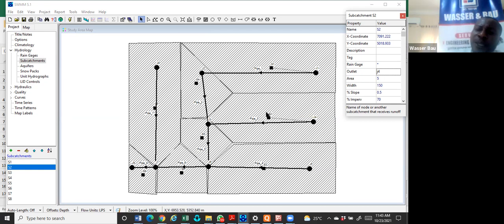So you know, gentlemen, the water that is coming from your house, when it comes out of your house, will enter the first manhole in front of your house. The water from your streets, when it leaves your streets, will enter the manhole on the road, on the major expressway. I want us to put on our imagination. So every catchment, water that is coming from Adeosun Street, Ozumbambadiwe, for instance, there's a particular manhole in front of Ozumbambadiwe that the flow will enter. So from that hole, it will then enter the pipe. So it is important that you identify the manhole closest to the catchment. That will be the receiving manhole.